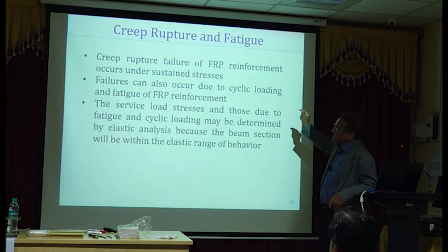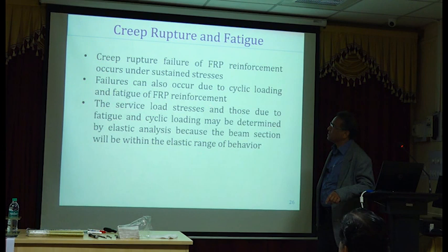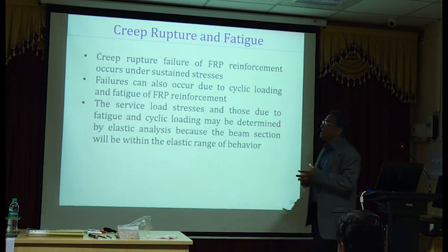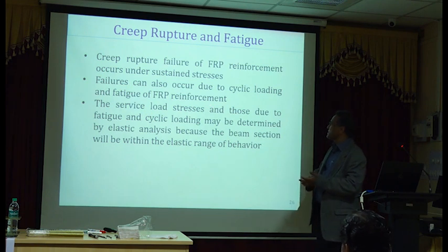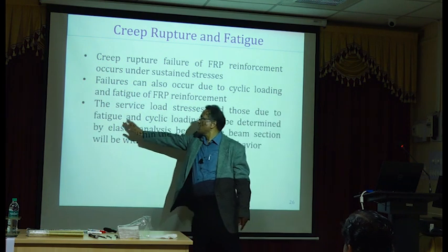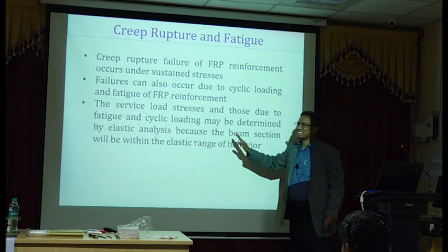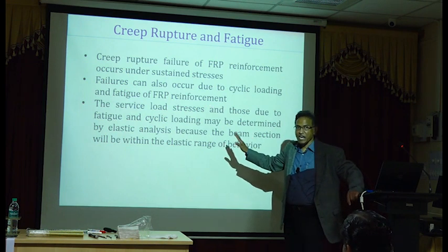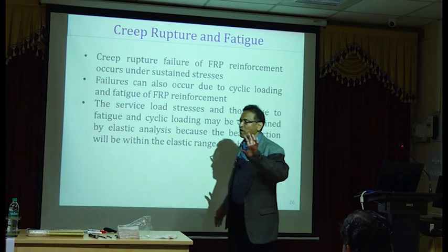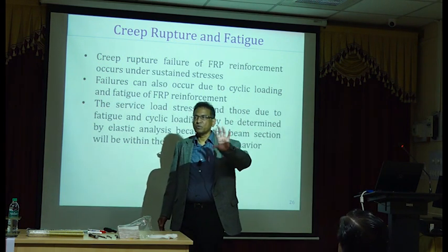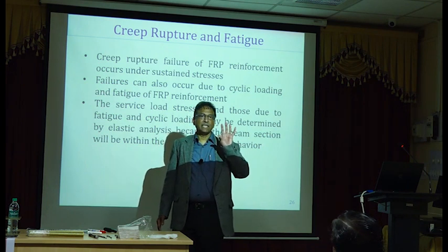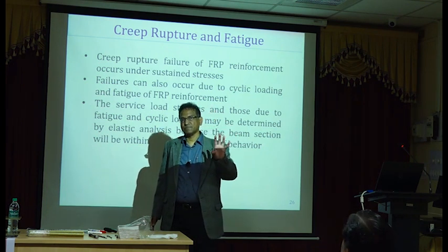Even in fatigue loading, similar effects are normally seen. So we need to calculate the service load stresses and compare them with the stresses permitted under creep and fatigue loads for FRP. For a given sustained load or fatigue load, we find the stresses based on elastic analysis.